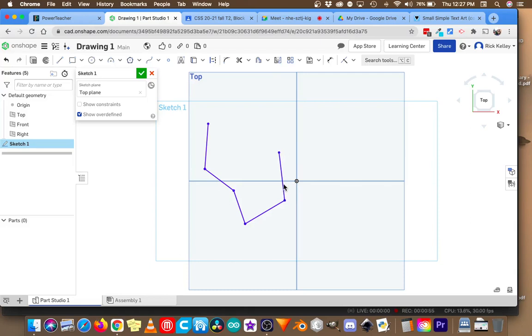Onshape is really not a huge fan of you just randomly eyeballing, clicking, and dragging stuff around. There's always something connected to whatever it is you're dragging. So you're potentially going to change more than you anticipated changing. Hey, look, I can get away with that first point. That's about it. The best way to change things is to dimension all of these parts and then change the dimensions. You can get the dimension tool up there.